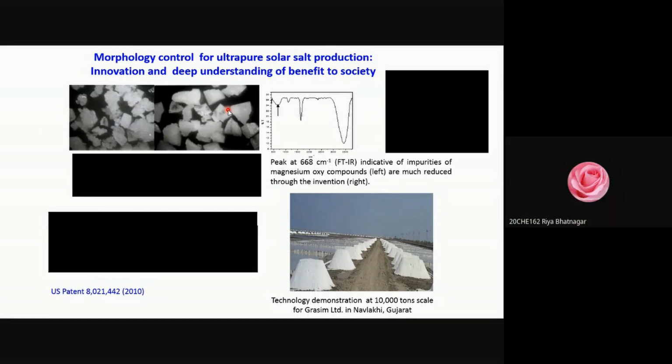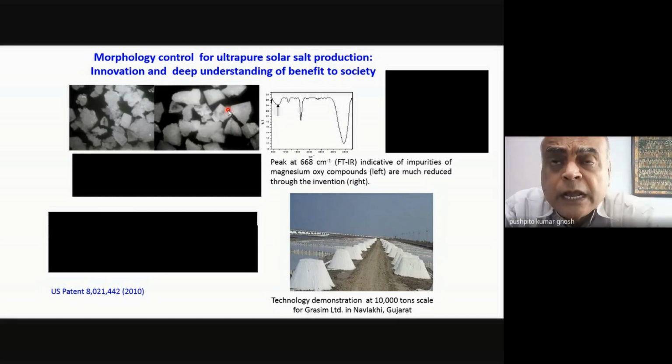Saturation, that's good. Of course, the salt comes out only after you reach saturation, right? As I told you, NaCl solubility doesn't change much with temperature, whether it's 30 degrees or 40 degrees. Once you have reached saturation and you are evaporating more water, then necessarily the NaCl must come out. You are really already operating at a saturation point.